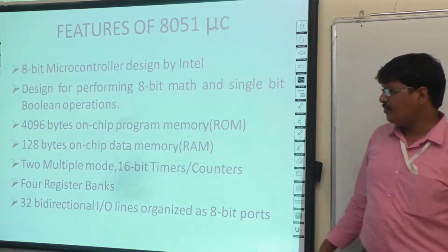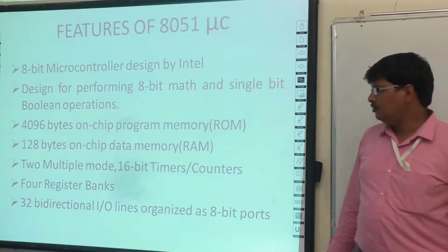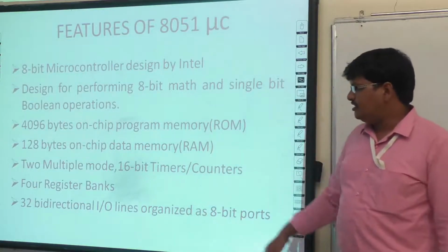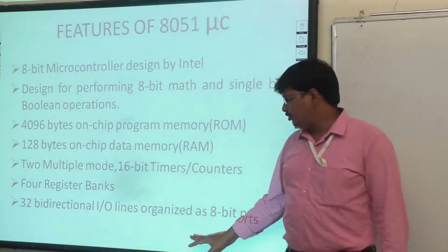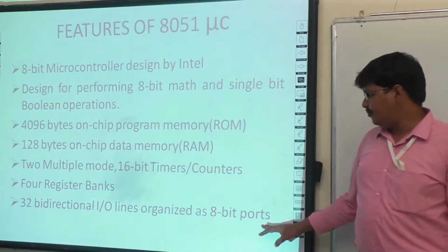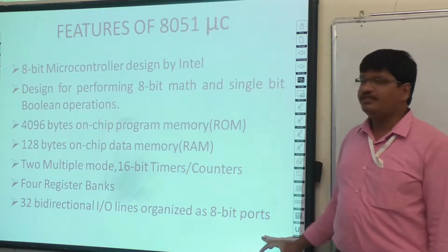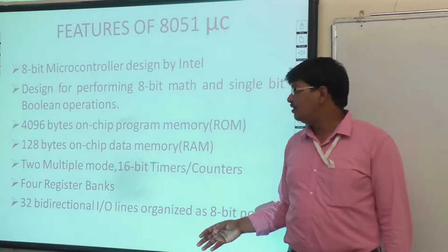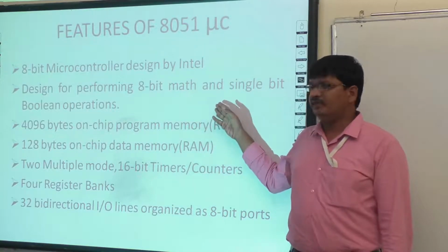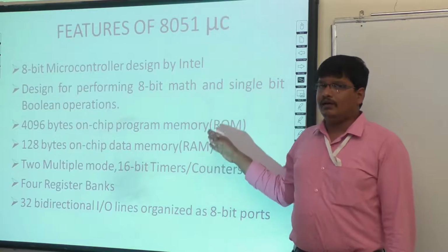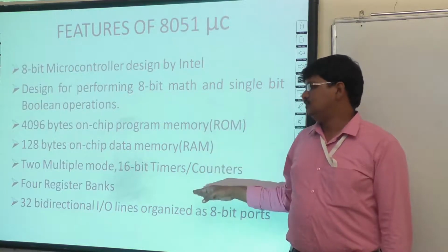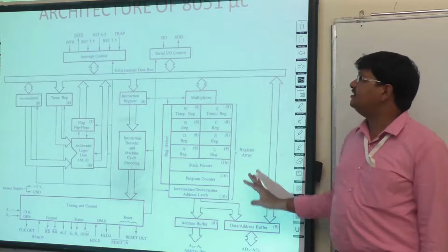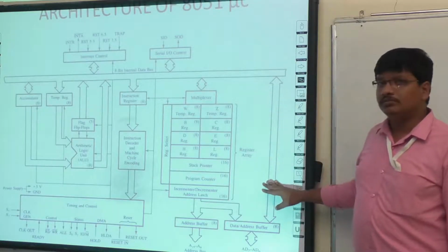Apart from that, it has two multiple mode 16-bit timers and counters, 4 register banks, and 32 bidirectional input-output lines organized as four 8-bit ports. These are the special features of the 8051. Based upon the application where we are going to use a microcontroller, vendor companies will design the allocation of RAM, ROM, registers, and input-output units.